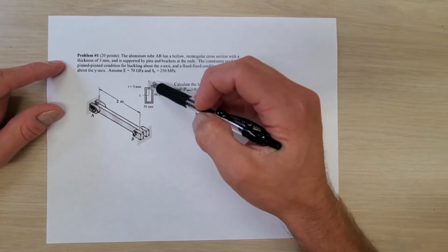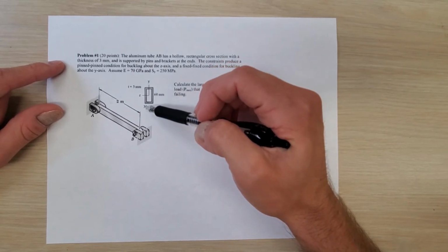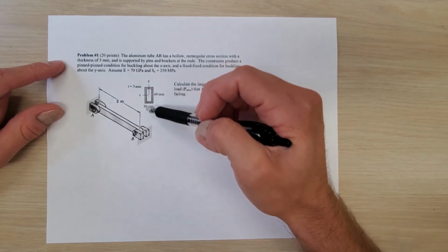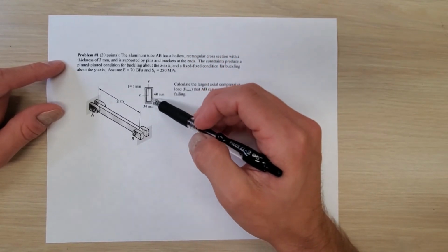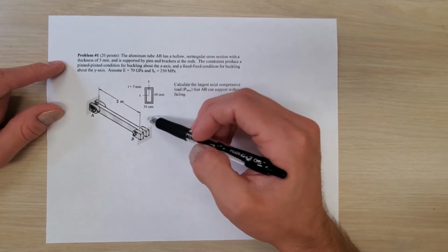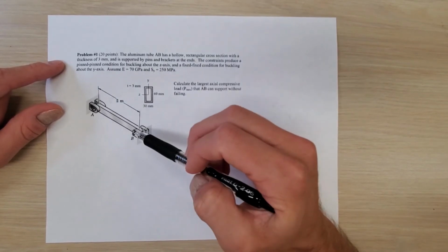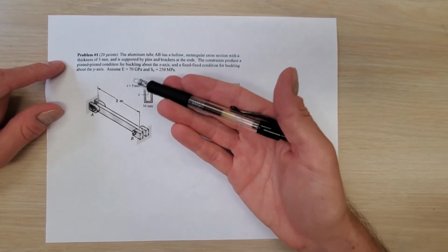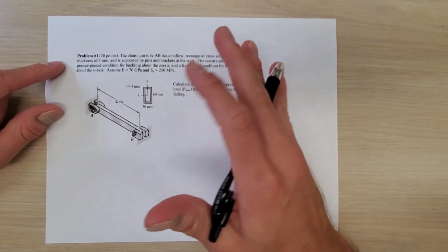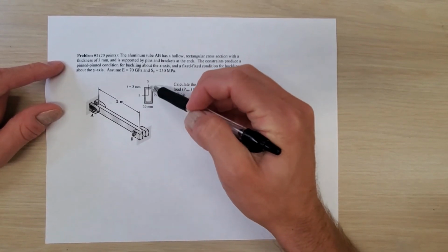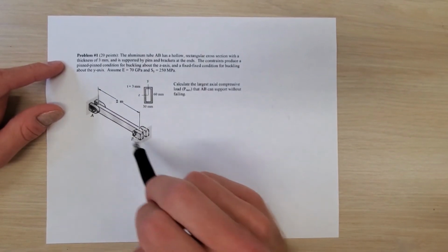Now usually, you might only need to consider one of those. But because here we can see that the moment of inertia about y is going to be the easiest axis to buckle about, it's going to be lower than the moment of inertia about z. We might say, oh, we only need to consider y-axis buckling. But because the y-axis is the fixed portion, it's actually going to be more difficult to buckle about the y-axis than the z-axis. So as a result of that kind of discontinuity there, although the moment of inertia about the y-axis is lower, its end conditions will make it more challenging to buckle.